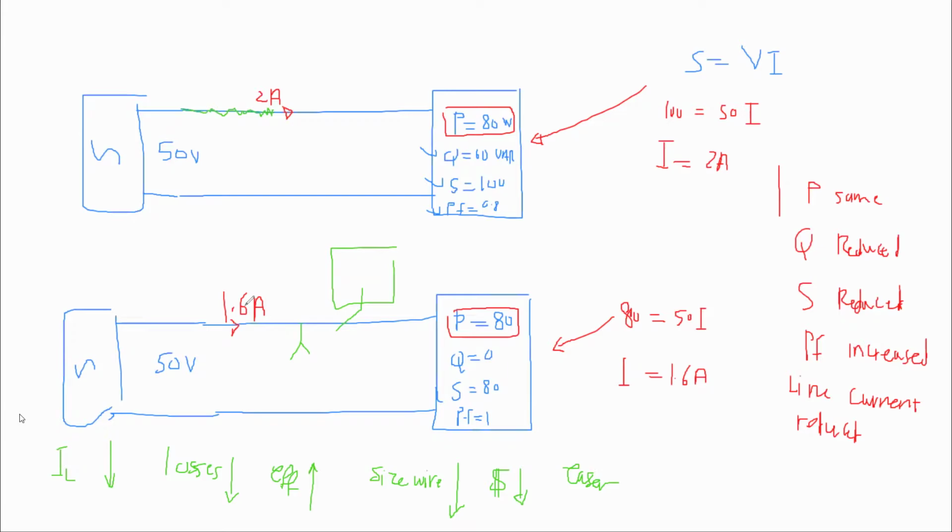So when we increase the power factor, we keep the real power. We don't change it, because if the motor needs 100 kilowatt, we'll always need the 100 kilowatt to work. So how do we increase the power factor? By reducing S. How do we reduce S and keep the same P? We reduce Q. Now, when we reduce Q, we reduce S, we increase the power factor, we reduce the current coming to the load. Is this okay so far?